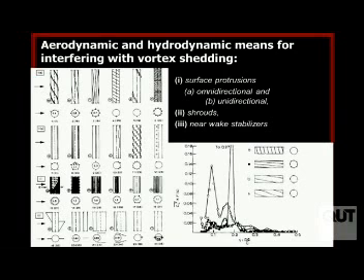They might be helical strakes to disturb the flow around the top, to create more three-dimensionality of the flow. There might be porous shrouds, a whole range of different ways of treating the response. And so you, again, see this idea of a graph of response versus frequency, and I go from a peak under a certain type of resonant condition. I drop that down completely by creating this spiral effect.